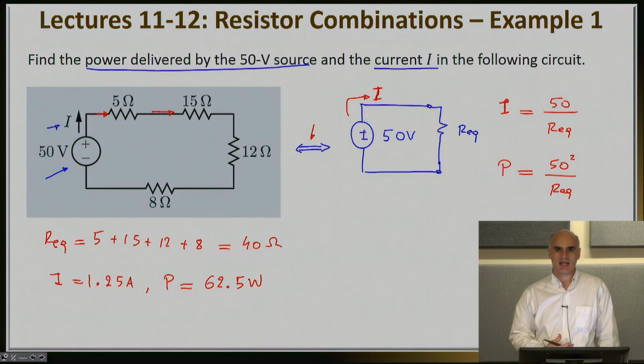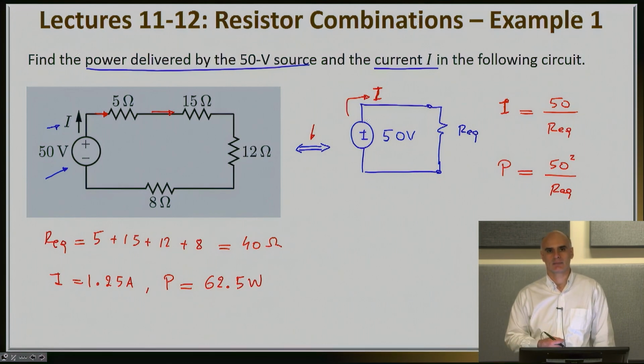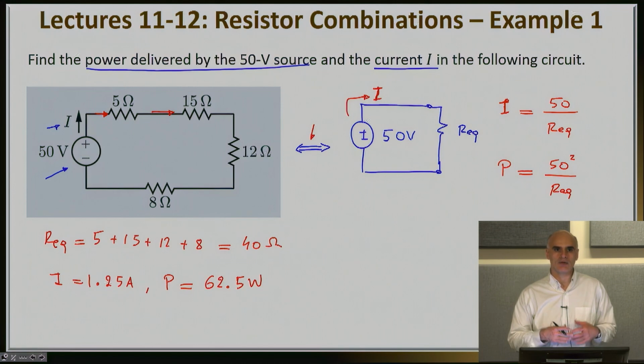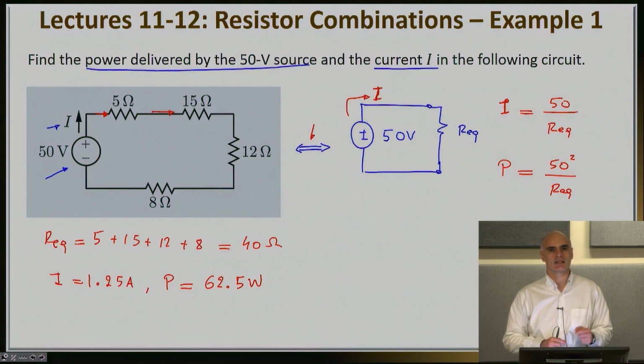If the answer is yes, then you're definitely guaranteed to have a series connection, because the series connection is by definition one in which the current is the same. It's not the one that simply looks like it's connected in series. It must satisfy this condition. A series combination, as we learned in theory, must satisfy that the amount of current is the same.